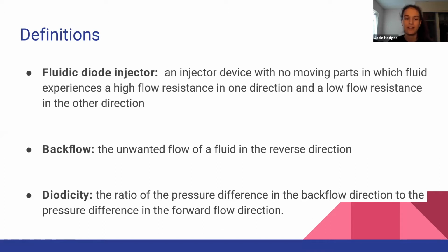And diodicity, the measurement I'm taking from all of the data, is the ratio of the pressure difference in the backflow direction to the pressure difference in the forward flow direction. I focused a lot on diodicity to compare pressure drops across each separate injector in my project. That's how I got all the information I needed.